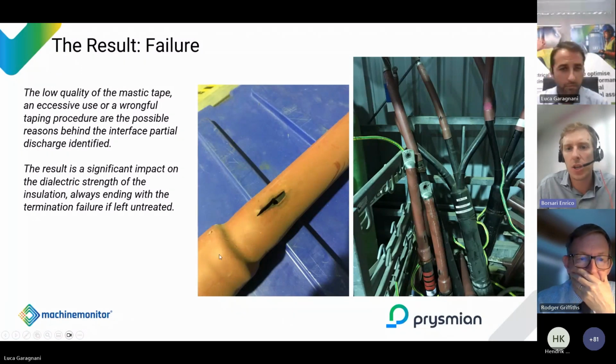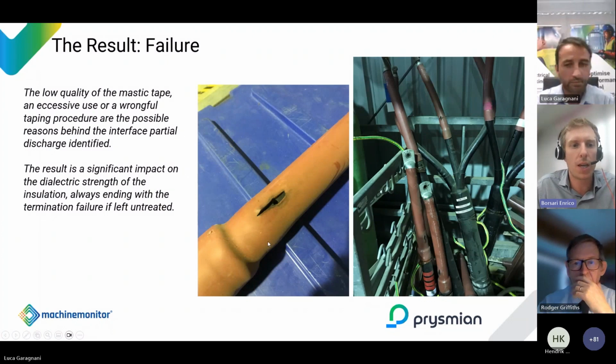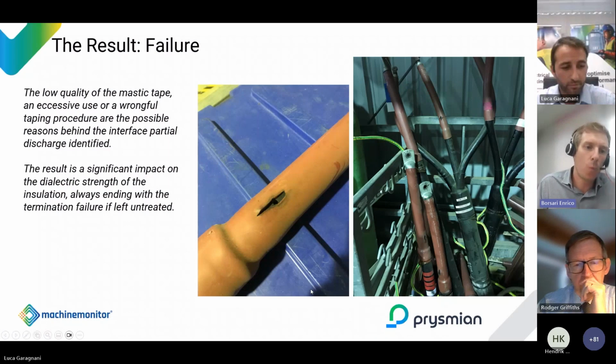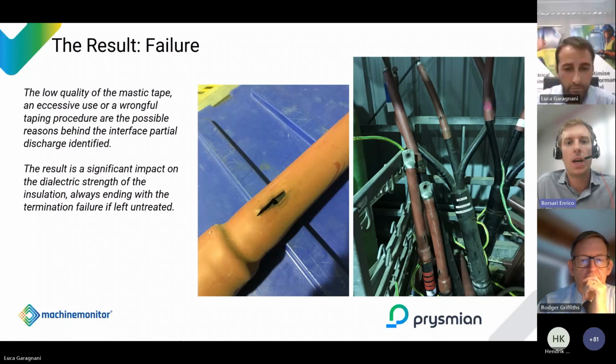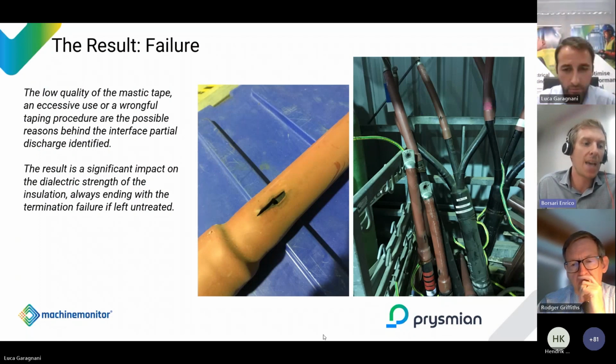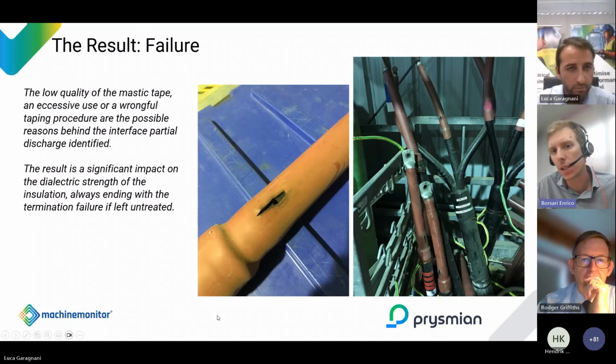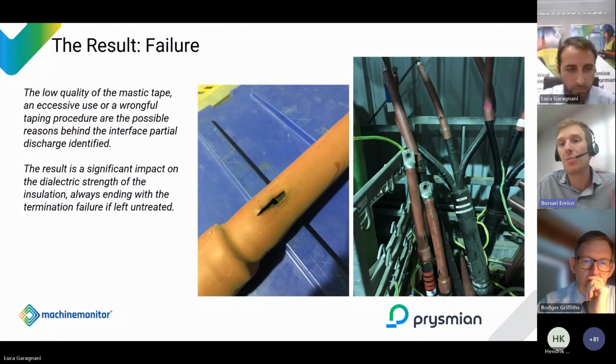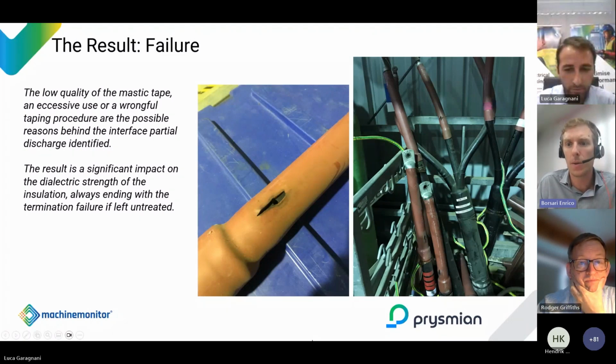So in a nutshell, I think the message from our side is we always try to push for preventive maintenance way before the PF curve or into the PF curve, but we always try, as Prysmian, to conduct preventive maintenance rather than reactive maintenance. So increase the reliability and the life of the asset before the PD becomes an obvious failure. I think that's it from my end, Luca.